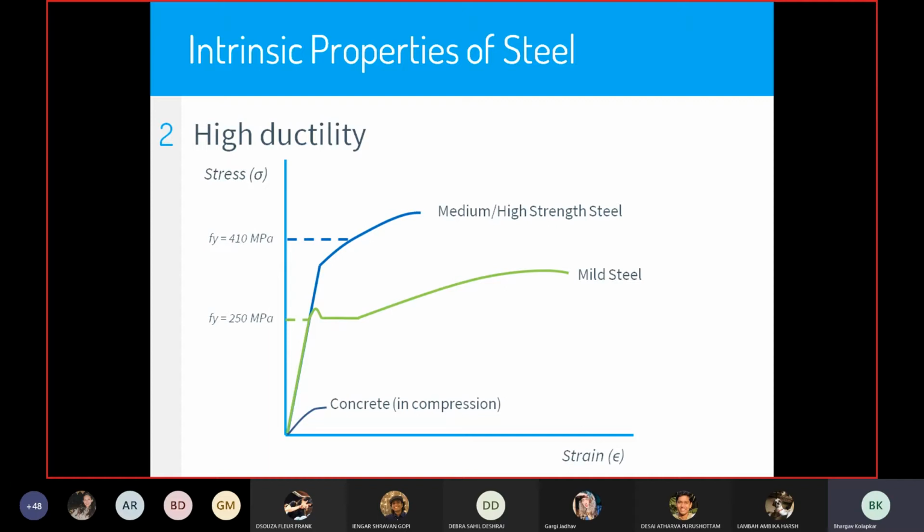Earthquake induces all forms of stresses in members, so it's not necessarily that we go with a ductile member only at the locations where we anticipate tension, and we don't differentiate into members that need a ductile behavior and those that do not, because every member does, every connection does, and that's how the entire structure gives a ductile response. So the bottom line is we really don't categorize which members need to be ductile.